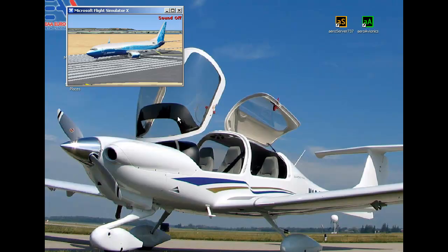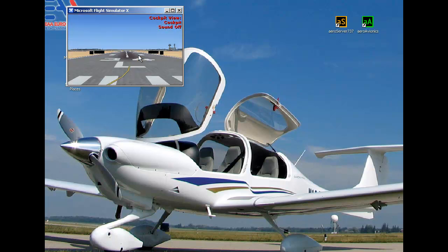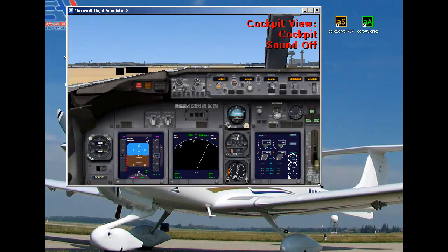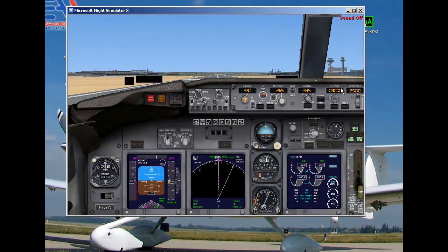One other thing I should mention that's quite important is that the system's been set up for the default aircraft, the 737. It may work with other aircraft, with other flight models. It probably will, but if in doubt, use the default model. What we also need to talk about is the autopilot inside Flight Sim itself. So I'll bring up that autopilot. Don't touch any of the autopilot system whatsoever in Flight Sim, because the Aerosoft avionics package will actually interfere with it.